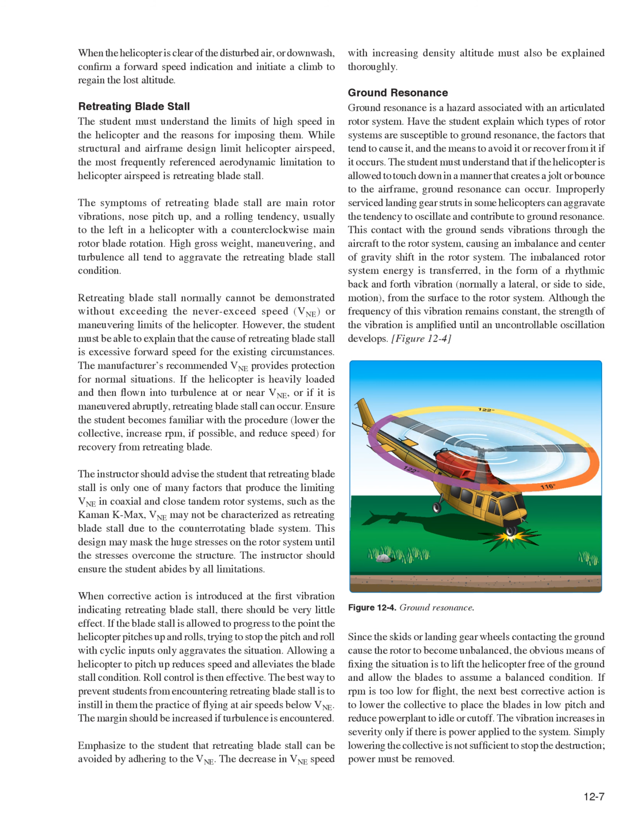produce the limiting VNE in coaxial and close tandem rotor systems, such as the Kaman K-MAX. VNE may not be characterized as retreating blade stall due to the counter-rotating blade system. This design may mask the huge stresses on the rotor system until the stresses overcome the structure. The instructor should ensure the student abides by all limitations.